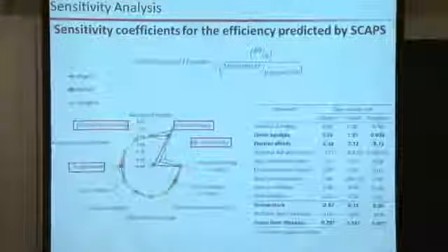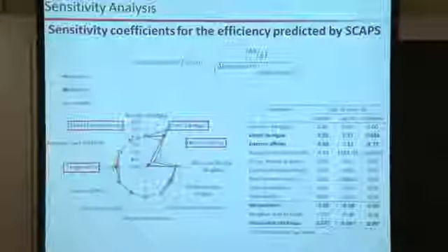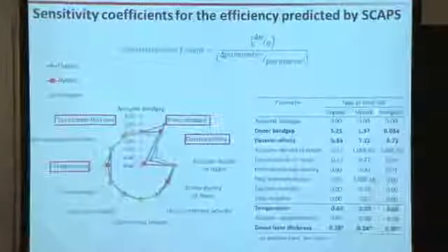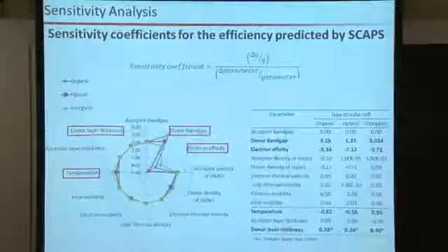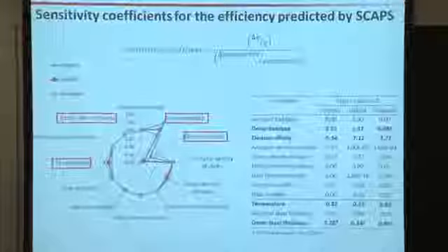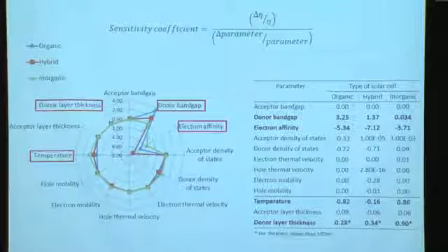We also, to determine the critical parameters which influence the performance of the solar cell, calculated sensitivity. Sensitivities are calculated from the change in efficiency observed by varying parameters, simulation parameters, or material properties. They were expressed in terms of the 1% change of efficiency in the parameter relative to the basis value.